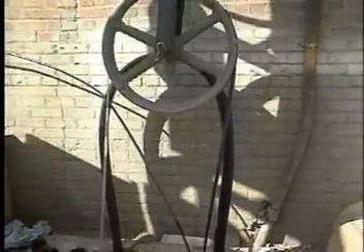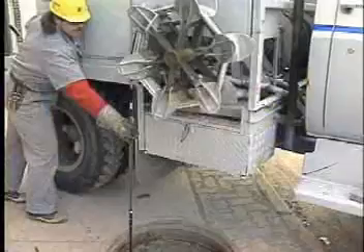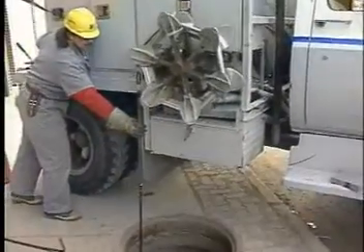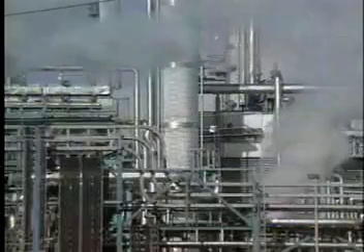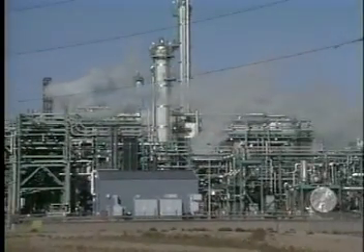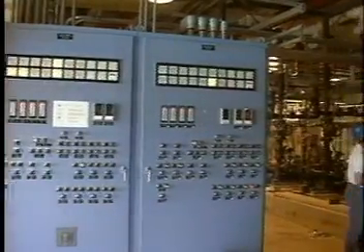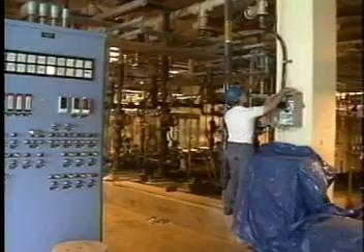In most urban areas today, copper cabling has filled existing ductwork to capacity. By using smaller fiber cables, efficient use of inner duct space is ensured. Explosive environments present in chemical plants and oil refineries are perfect for fiber transmission systems. Because fiber does not carry electric current or radiate energy, it is the safest and most efficient method for providing connectivity in these applications.